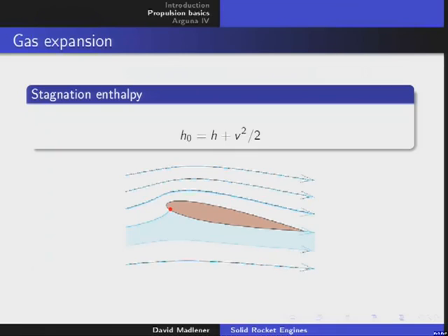And this is very important because this is directly connected to the temperature by this relation. So if you know the specific heat at constant pressure, you just can calculate the enthalpy by multiplying it with the absolute temperature. And as you have seen, for ideal gas, we can calculate that. So you can calculate from this equation by dividing by Cp the temperature of the tip when you go through air at a certain velocity v. Okay? And you can see by calculation that at velocities larger than about Mach 2.53, the temperature gets so high that you really have to think about how to build the tip, otherwise it will just melt away. Yeah? So reaching temperatures of about 500 degrees. You cannot take aluminum, it's not possible.